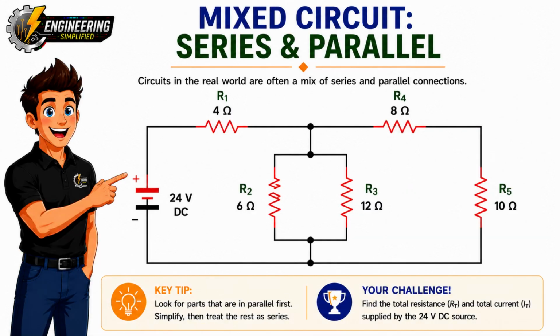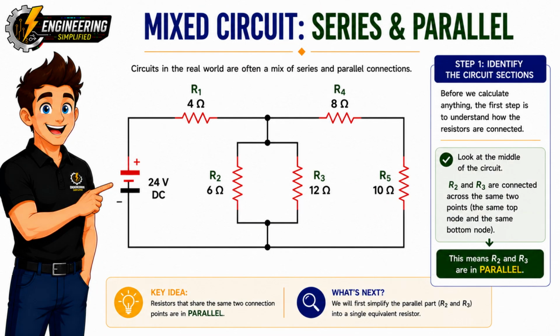Now it's time to put everything together. So far, we've learned how to solve series circuits and parallel circuits separately. But in the real world, most electrical circuits are actually a combination of both. These are called mixed circuits. The key to solving them is to break the circuit into smaller sections. First, identify any resistors that are connected in parallel and replace them with a single equivalent resistance. Then, continue simplifying the circuit until only one equivalent resistance remains.